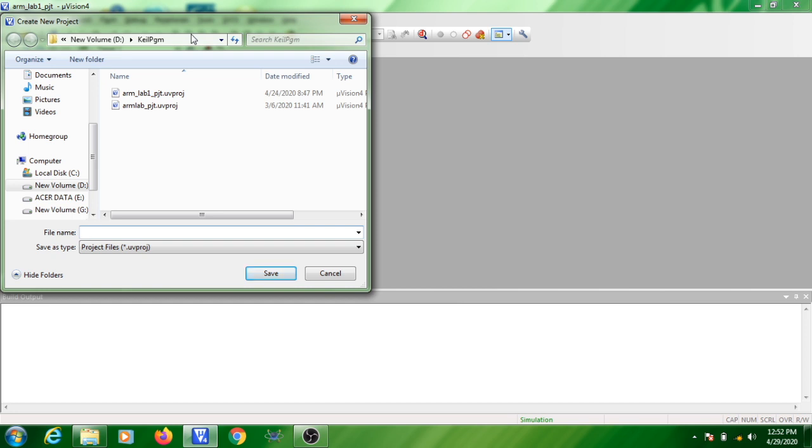So first what you need to do is create a project folder, because while you are creating a project there will be so many files associated with it. All these files should be kept in a project folder. The first step is to create a project folder. And one more thing you need to keep in mind: this project folder should be created under one of the drives directly. Don't create it on the desktop, downloads, My Documents, etc.